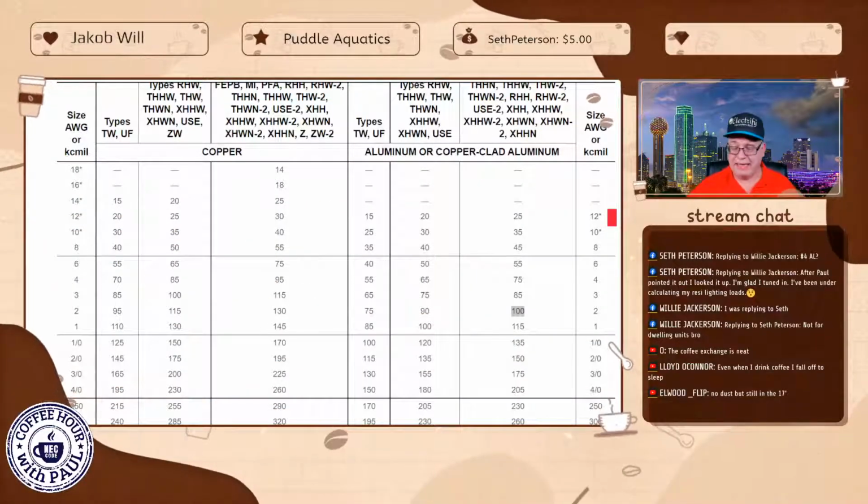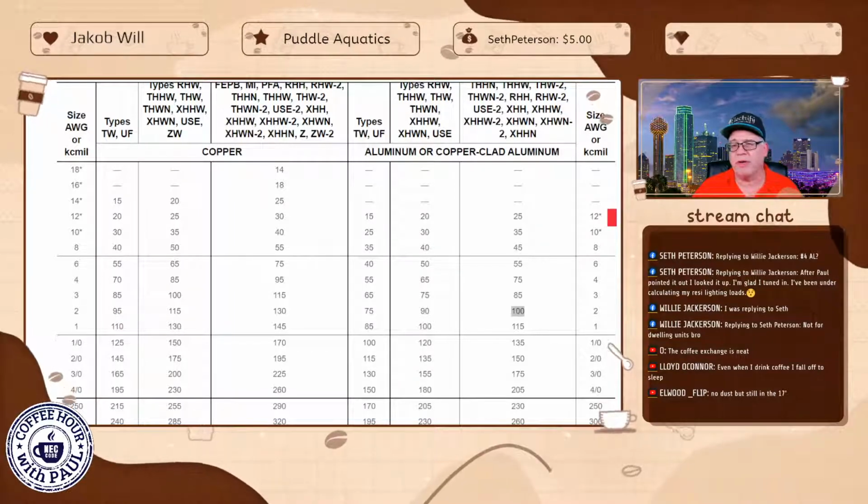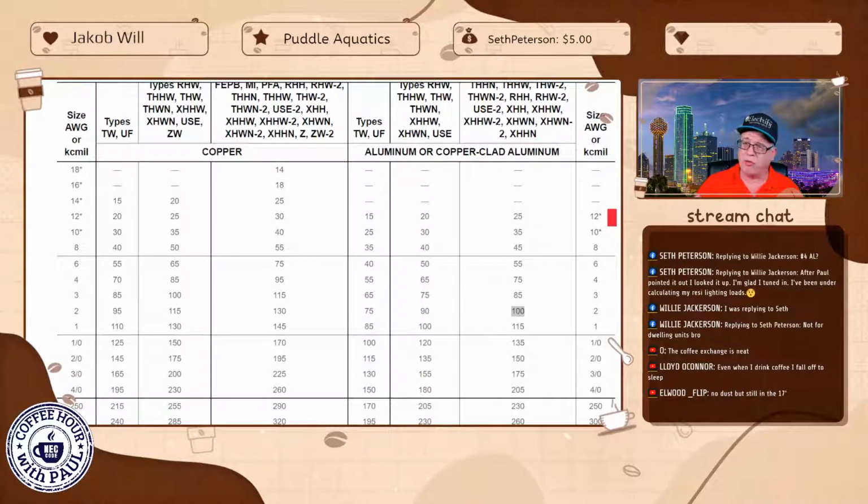All right, guys, well, that's just about it. It's just that simple. Just remember, when you're doing an optional, you could have other things thrown your way. Just take your time. Work through each little piece. If you have an additional appliance, an additional thing with a nameplate, or additional something with a motor, and it's not covered in the B portion of 220.82, then guess what?